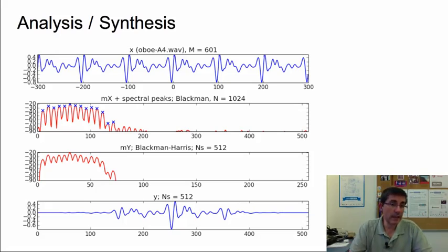And then we basically do an additive synthesis approach in the frequency domain by generating main lobes from these peak values, from these peak locations. The FFT can be a different size. The window in this case is a different one because we're using a Blackman-Harris window. And then we do the inverse of that. And hopefully this resynthesized sound is identical or similar to the original one, of course, with now the idea that we have a Blackman-Harris window applied to that.